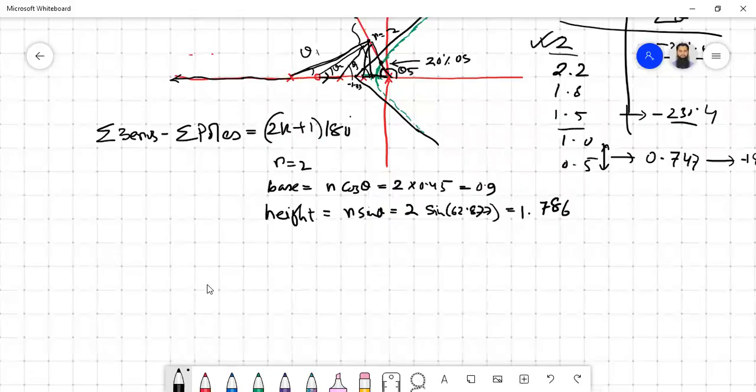So theta minus theta 1 plus theta 2 minus theta 3 minus theta 4 minus theta 5. So basically, minus theta 5 can be, we can use the 180 degree minus the angle formula for that. Okay, so this summation has to be equal to 180 degrees. So we have to check whether it is 180 degrees or not. If it is 180 degrees, then that particular point is on the root locus. But if it is not, then this point is not on the root locus.